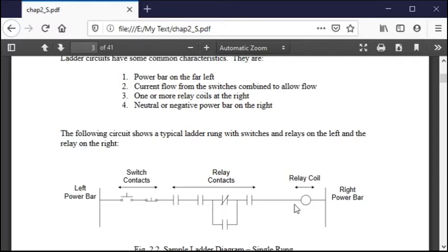Because if this device were over here on the left, and let's say, for instance, something that has happened and does happen is that the wire on the left side fell off and touched a ground or a neutral, this device would turn on without all this logic having been executed, and that's not good. Especially if you're sitting there with a motor starter and you're pushing a button and the motor won't turn off, it's running no matter what you do, you're really in a danger situation.